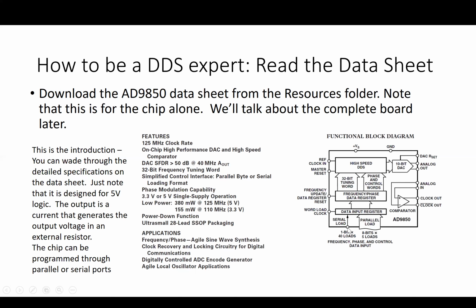But the serial load, by sending a set of preparatory pulses along here, you can get this thing to be ready to accept data, and you will actually soon see the resets, the frequency update, clock load, and data pins being used to do exactly this. Just a word of caution, of course, the pins on the chip data sheet have nothing to do with the pins on the board you're going to order.